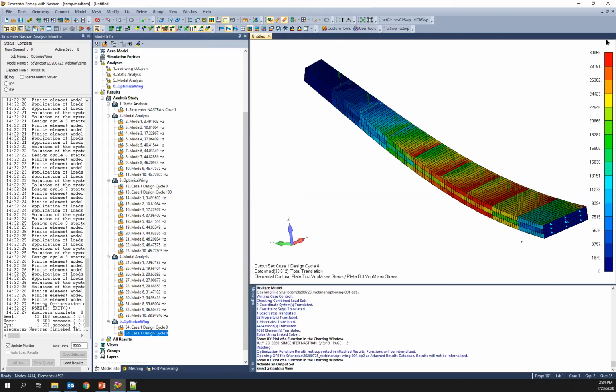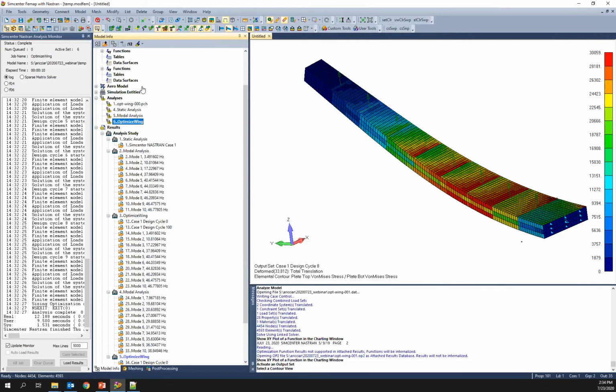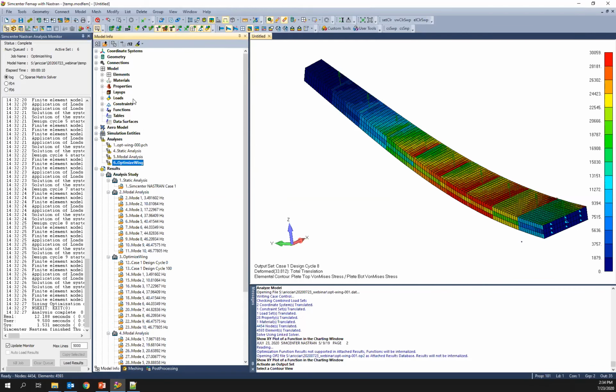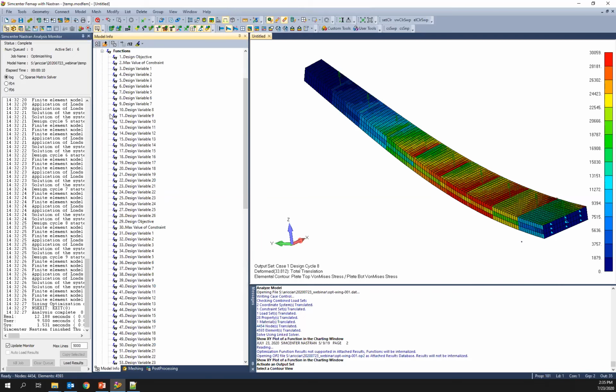So this is maybe a more intuitive result than the previous result, where really the material design was being dominated by that frequency constraint. It was adding material to stiffen up the wing. And in this case, that constraint's not there. And so this is the active constraint. And this should be a lighter design than the previous design. So maybe this is a trade-off you could do if that 8 hertz is just sort of arbitrary and you're trying to avoid dynamic problems or controls problems, and maybe it's worth dealing with if you can save a lot of weight. And we can see the difference here.